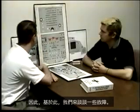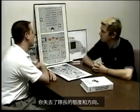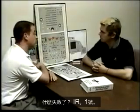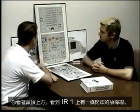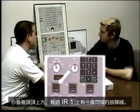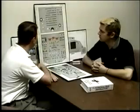So based on that, let's talk about some malfunctions. You lose the captain's attitude and heading. What's failing? The IR, number 1. You look at the overhead and you see a flashing fault line on IR1. That indicates to me that heading and attitude may be recoverable.